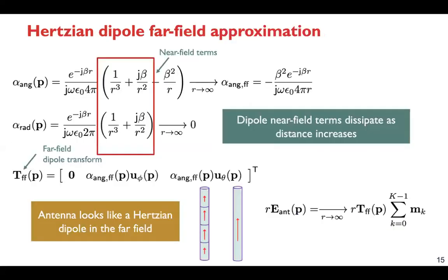Right. One important aspect of the development here is noting cases in which our approach, this electromagnetic approach, can be simplified to that array processing interpretation of the array manifold. Okay, and the way we do this is we start applying those assumptions that are needed for developing the isotropic manifold. The first is the far field approximation for the Hertzian dipoles, right?